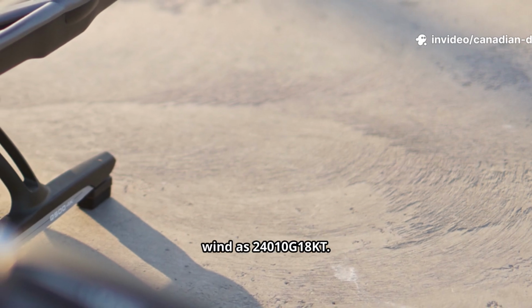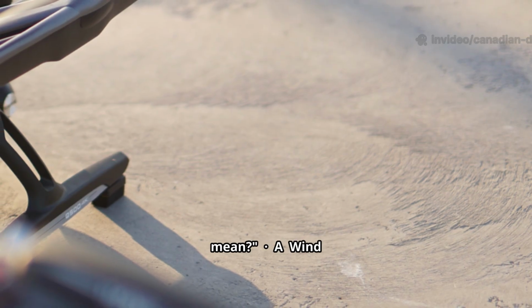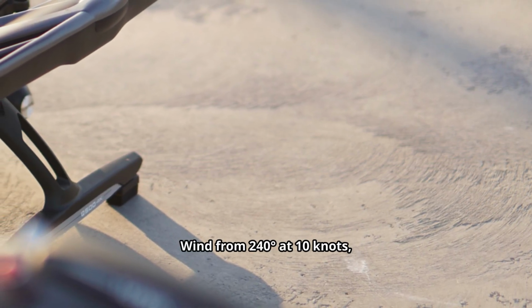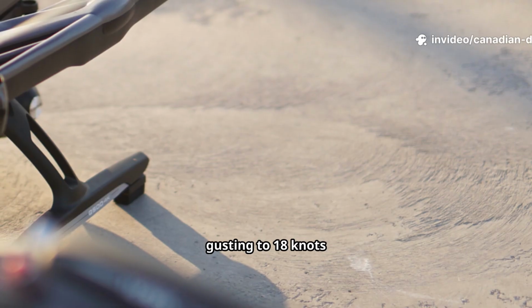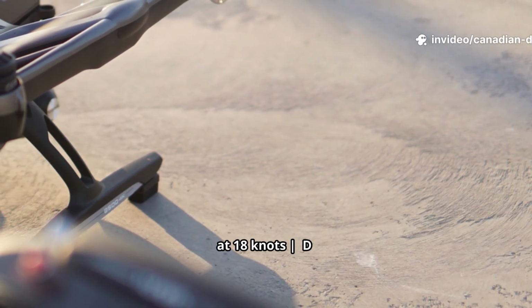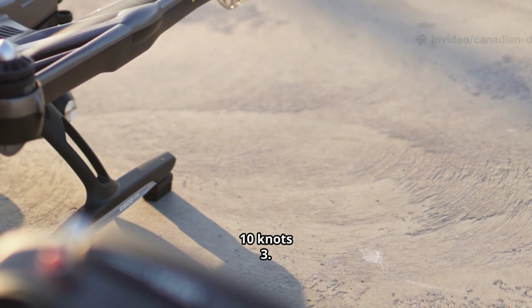2. The METAR reports wind as 24010G18KT. What does this mean? A. Wind is variable. B. Wind from 240 degrees at 10 knots, gusting to 18 knots. C. Wind from 240 degrees at 18 knots. D. Peak wind speed is 10 knots.